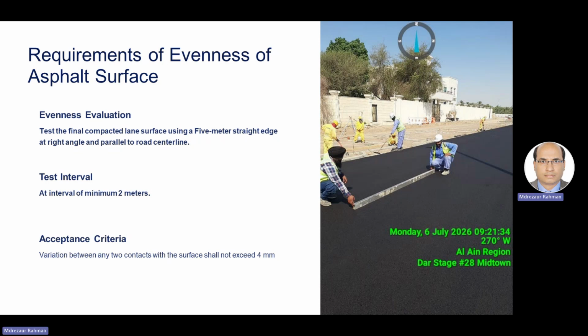But how will they ensure it's a straight edge? Should it be calibrated? Yes, the straight edge should be calibrated. We are talking about when you put the straight edge and you see this end and this end, there's a gap. I agree, then it is more than 4 meters.